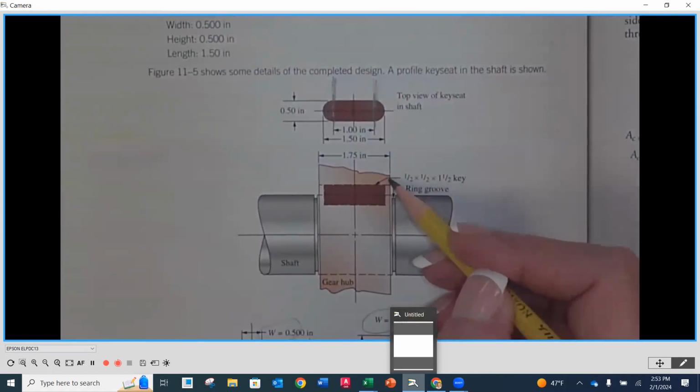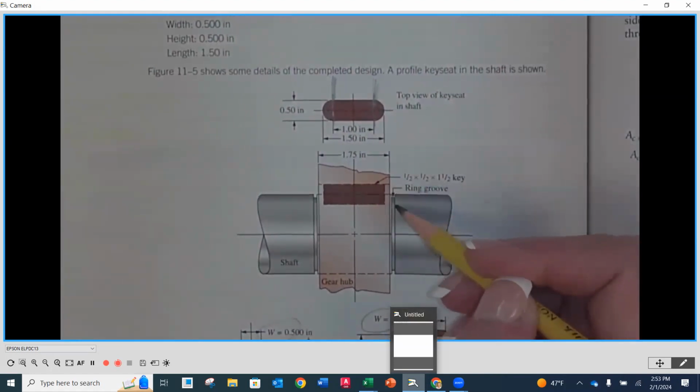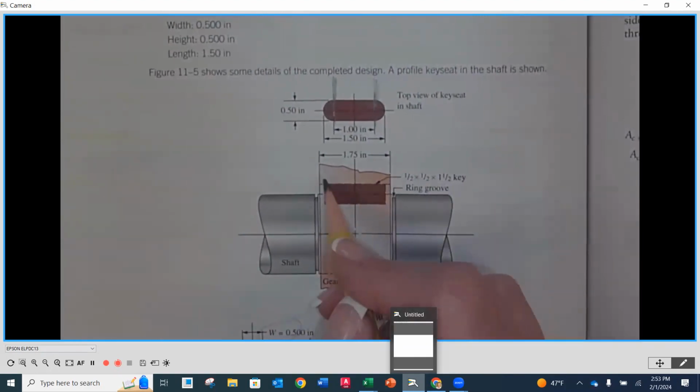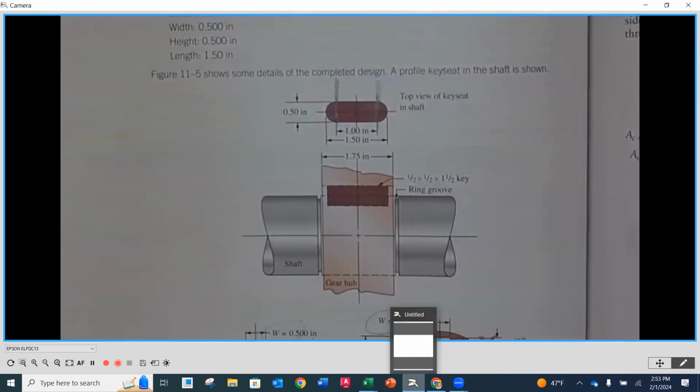The radiuses are going to go outside and they're going to interfere with the retaining ring. If they go into that retaining ring and we do shaft design, we now have a multiplier for our stress concentration. And now my diameter of my shaft has to get a lot bigger to accommodate that. You can't go out into the confines with any manufacturing process or any part of your key.